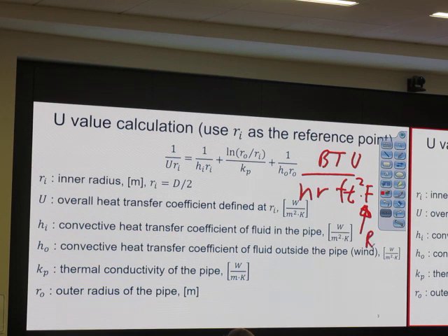Nothing, because the U value and K value depend on the temperature increment. An increment of 1 Fahrenheit is the same as an increment of 1 Rankine, okay? The only time that we use the absolute value is when we use the gas law, PV equals ZnRT, which has to be in Rankine.